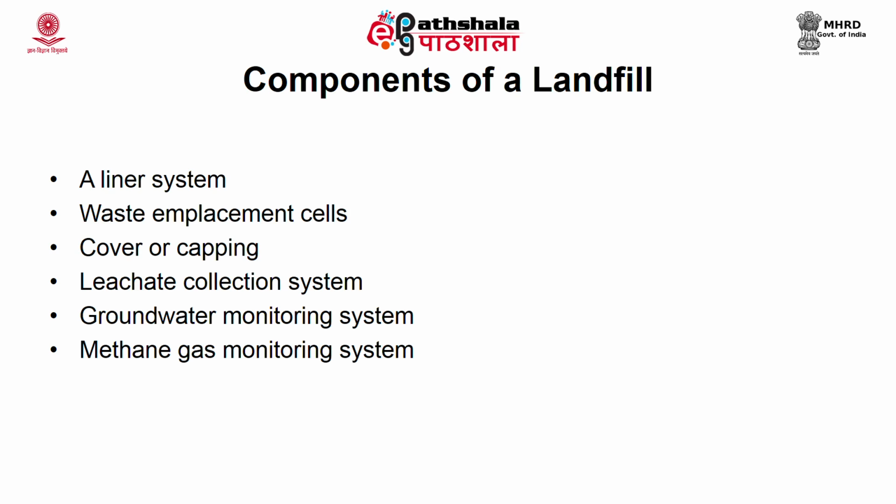Now, the groundwater monitoring system and methane gas monitoring system are for post closure. Post closure means once the landfill is done, there is no further space to accommodate the waste, then you have to close the landfill, or you can call it sealing the landfill. After that you have to keep monitoring the landfill continuously for 5 to 10 years, so that you can identify if there is any leakage, through these groundwater monitoring and methane gas monitoring systems. The details of these components of a landfill we will discuss in the next module.